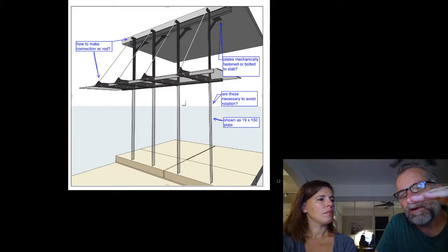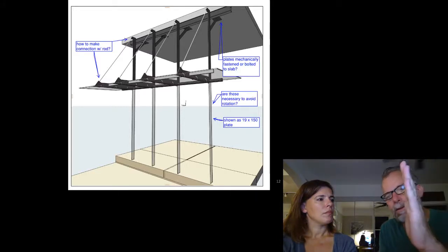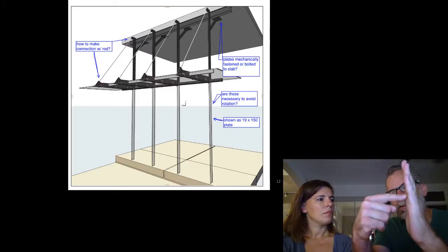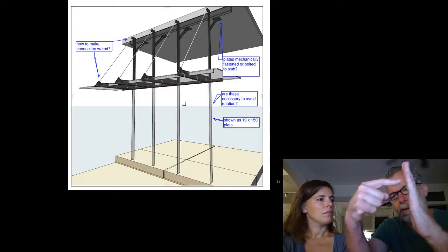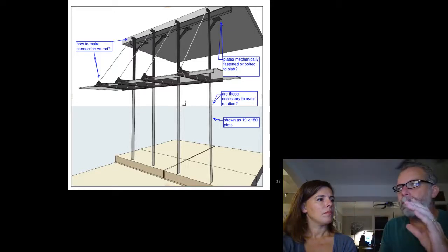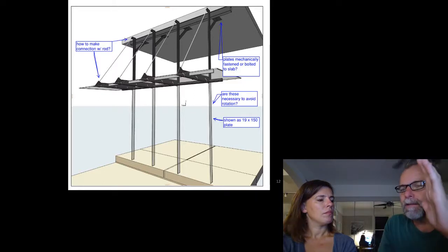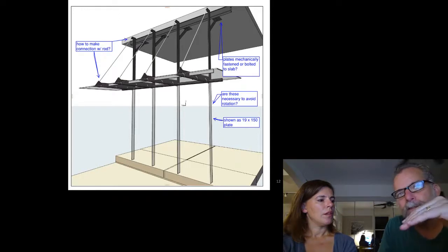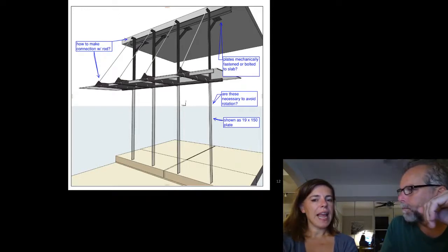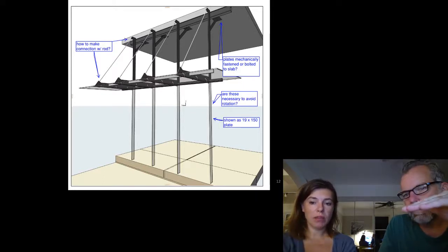And the argument was, whereas a flat screen, when we have wind blowing on a flat screen and it's trying to get through all the penetrations, there's a lot of volume of air that has to pass through the screen. And so a screen has to be extremely porous to have a meaningful reduction in load. You don't start to get any reduction in load until it's 25% porous.